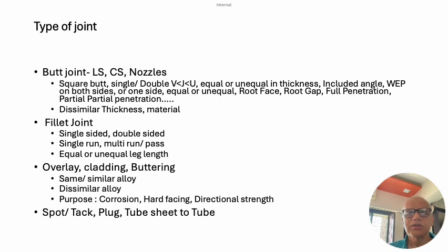So we must list out, for our job or for our type of product, the normally preferred joints or normally used joints in our manufacturing areas, and classify them to the extent possible, make a table, recommend for different materials, for different processes, for different thicknesses, for different positions, all the variables a welder is going to be concerned about, and also depending upon the filler metal, parent metal, and the resultant chemistry.